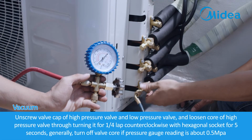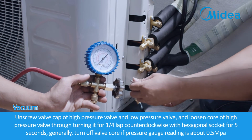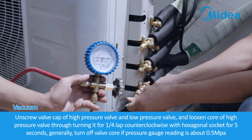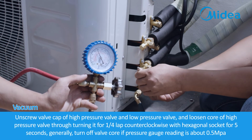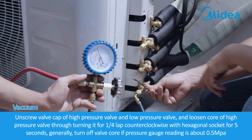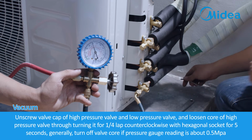Unscrew valve cap of high pressure valve and low pressure valve, and loosen core of high pressure valve through turning it for 1/4 lap counterclockwise with hexagonal socket for 5 seconds. Generally, turn off valve core if pressure gauge reading is about 0.5 megapascals.